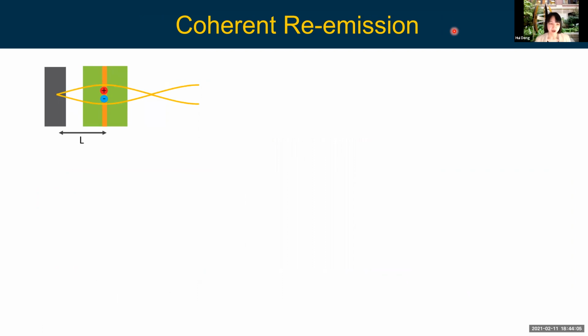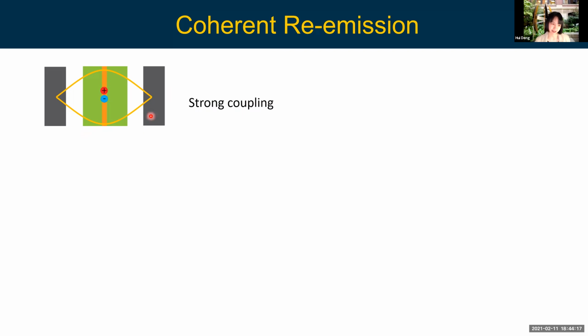So what that means is that we no longer have this very strong field enhancement from the cavity. How well does the cavity confine the field? If you think about two mirrors, let's say the reflectance is 99%. We actually typically need to use mirrors with a reflectance of 99.99% or higher in order to form those gallium arsenide polariton cavities.